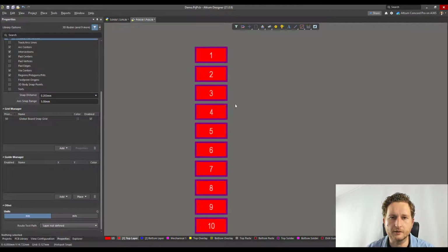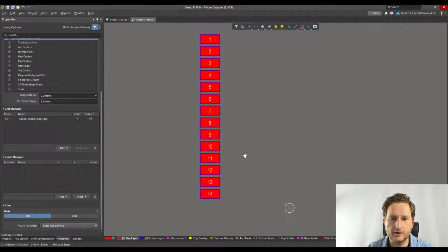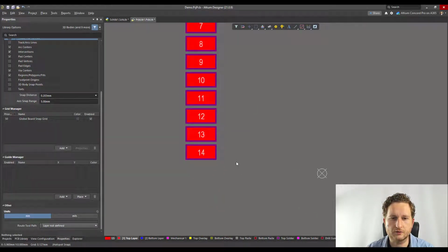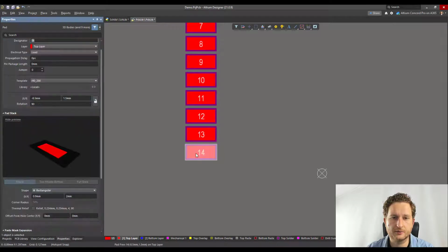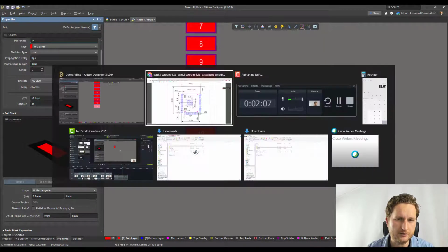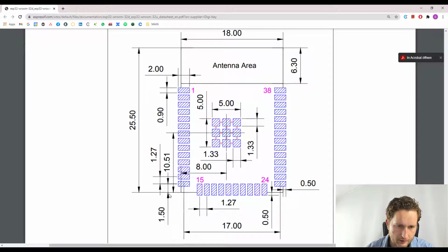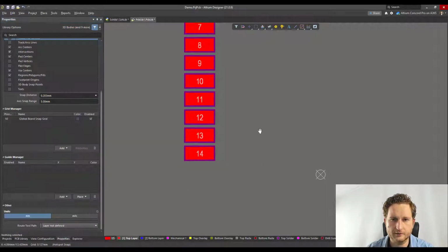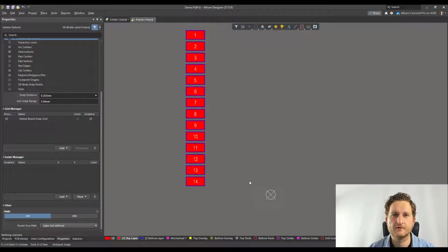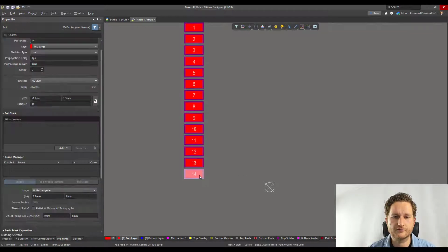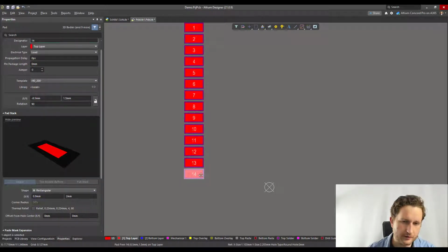Click in the middle on the pad. So, and now we can double check the coordinate of this pad here. It must be 1.5. Double check. The middle of this is at 1.5. Okay. So let's do the same for the 15th pad. Just simply copy and paste it.